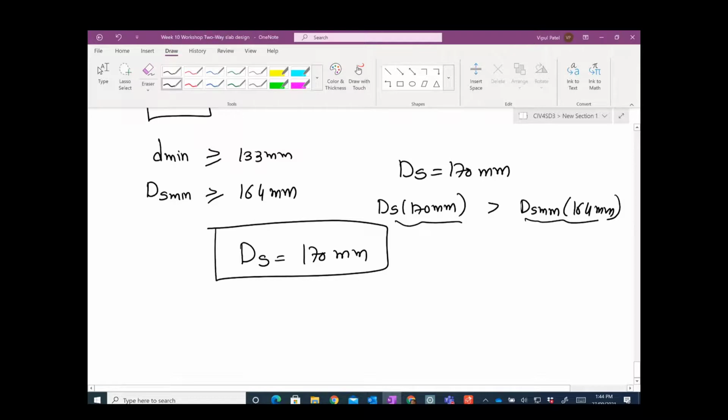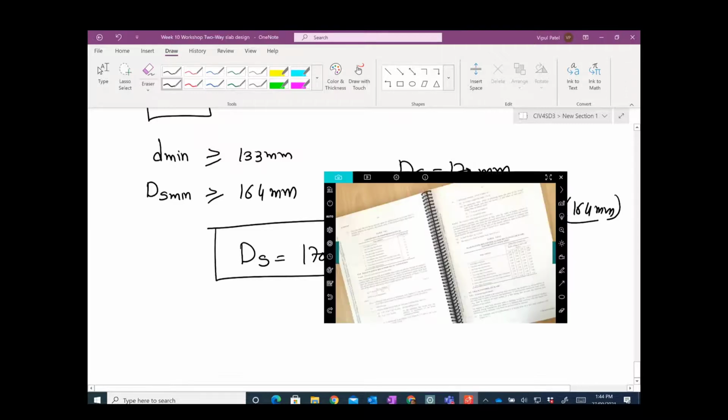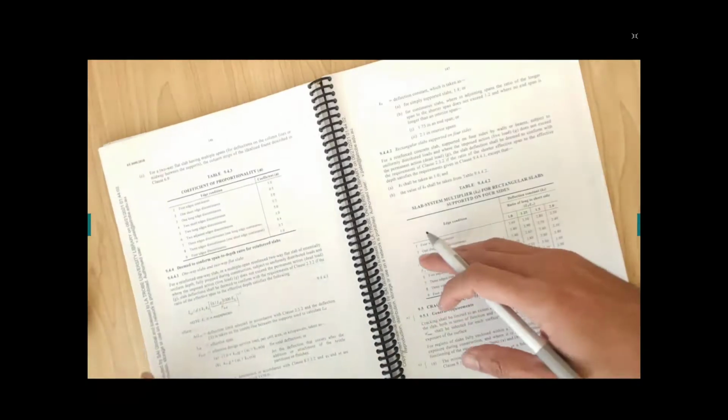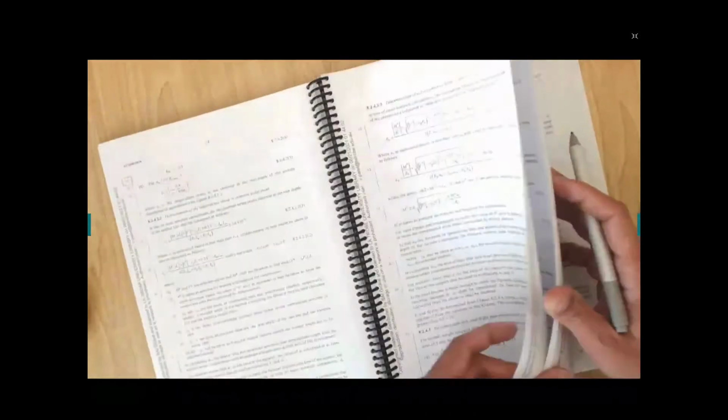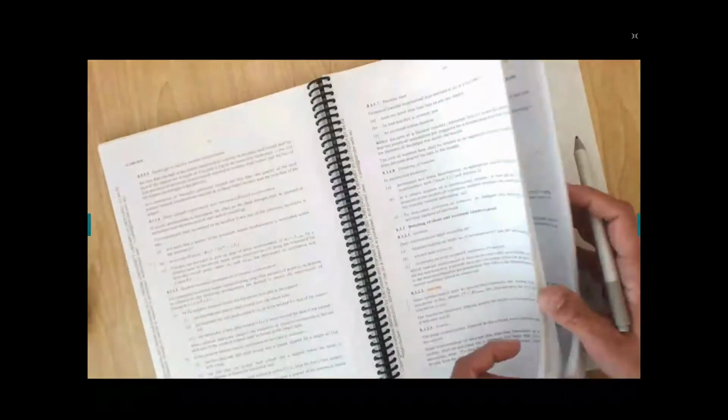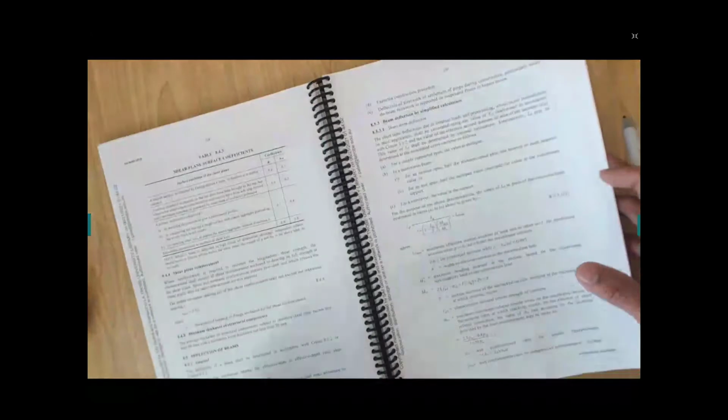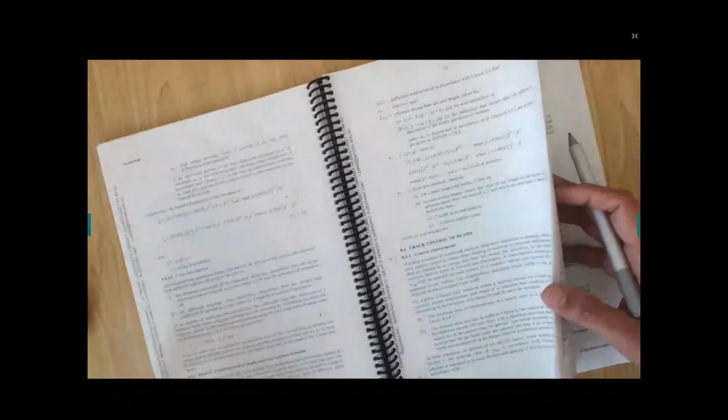Now look, in the real world, when you work in the industry, your supervisors, or whoever has chartered status, might say, look guys, 170 millimeters sounds good, it looks okay, but now we need to save some money. The standards have different methods for deflection calculations, and different methods will give you different answers, because there are some assumptions: refined calculation, simplified calculation, and deemed to comply.